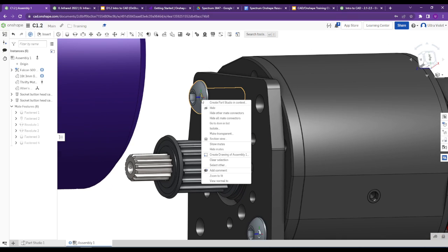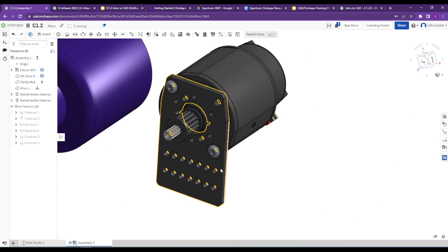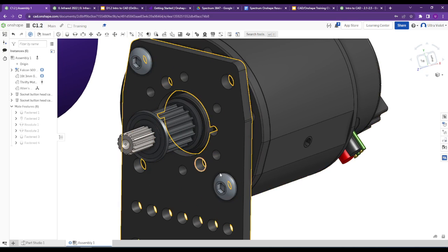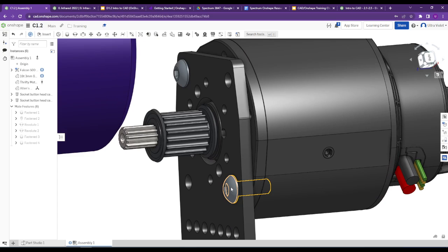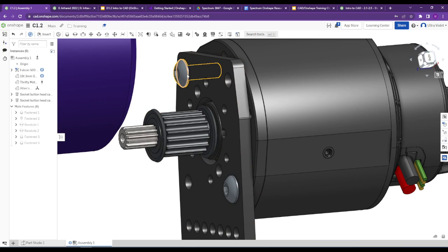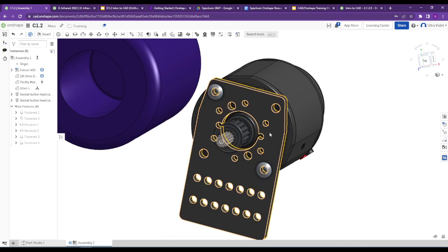So we have those bolts already lined up. I'm going to hide all the mate connectors, and now we have bolts there ready to go. So we can get a little bit more detail into our CAD just by inserting bolts. This helps especially if we want to make sure we're not having bolts run into something on the robot, or that they don't get in the way. We make sure we know exactly what size and length bolt we need. So it's super useful to have that ready to go without having to find it or anything else.